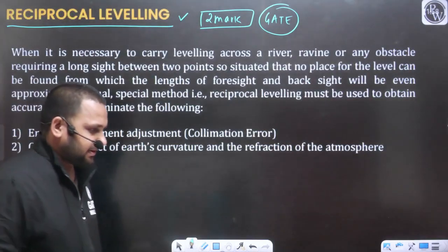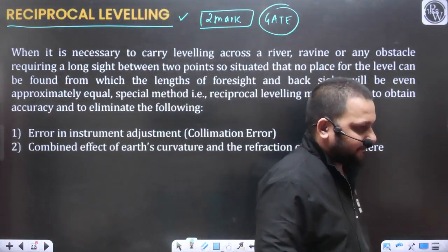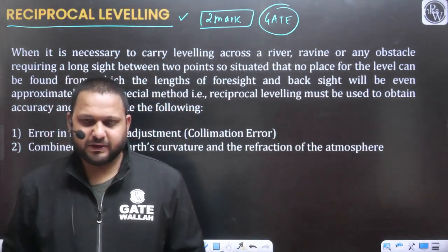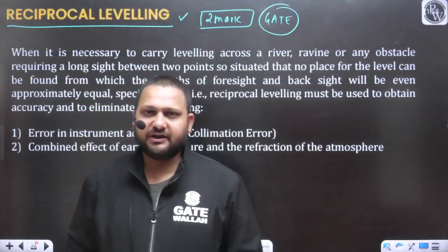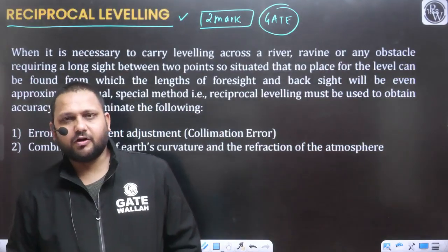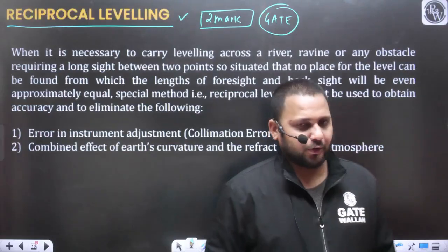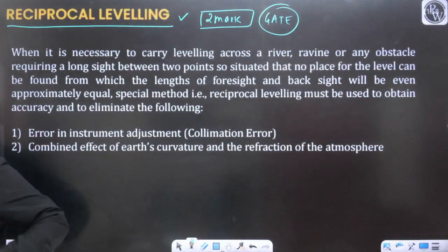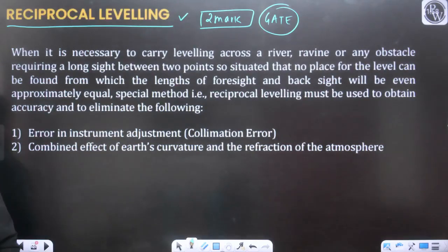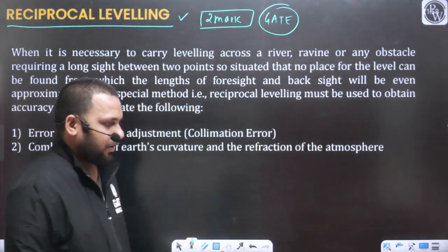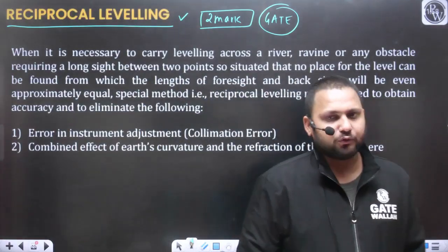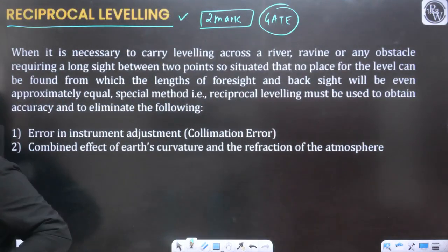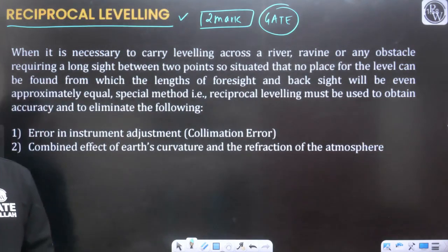Now one by one we will discuss all the aspects of the geodetic leveling. So this is the method of the leveling. Can you please tell me what was the objective of the leveling? I'm not talking about the plane leveling or the geodetic leveling; in general, what is the objective of leveling? Measure the vertical distance, or more precisely, define the reduced level of the point. Whenever I use the term reduced level, it by default means we are measuring the vertical distance from the mean sea level.